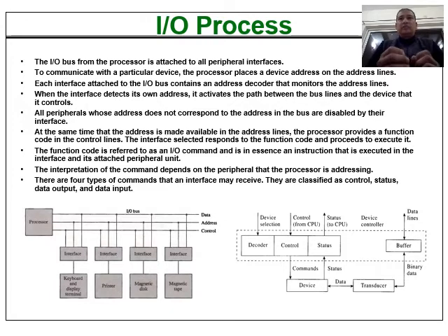So when the CPU wants to communicate with, let us say, the keyboard, it will take the address of this device, which in our case is address number 1, and put this address on the address lines. The address put on the address lines is read by the address decoder section of the interface.